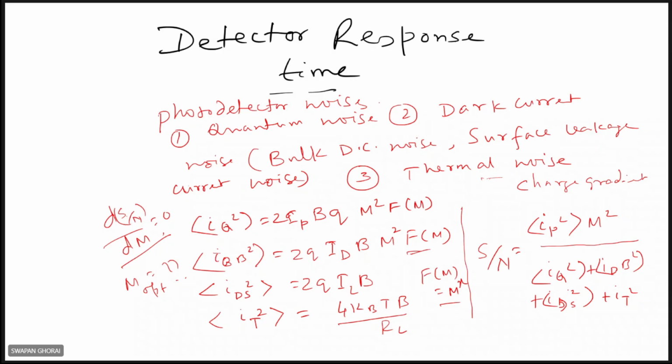When you use these photodetectors, you also have to consider photodetector noises. After the photodetector, the current is very small and has to be amplified. When photodetectors are used in fiber optic communication systems, the photodetector and its circuit should be chosen so that a particular signal to noise ratio is maintained.